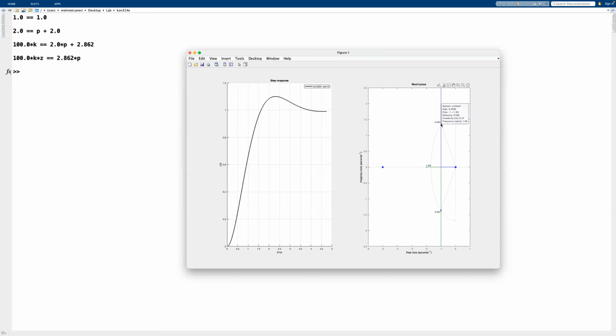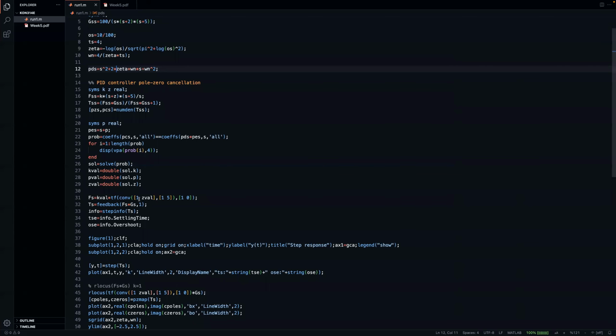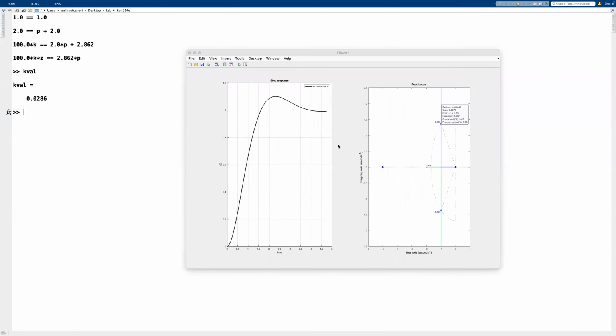And if I look at this, this is going to be the k value that I'm trying to use for my controller here. So something like this. And of course, k val is equal to the exact same value. So that was the reason why I separated the dynamic parts from the gain of the controller, so that I add only the necessary parts to my root locus, and I end up seeing the same gain value on the root locus and on my controller.